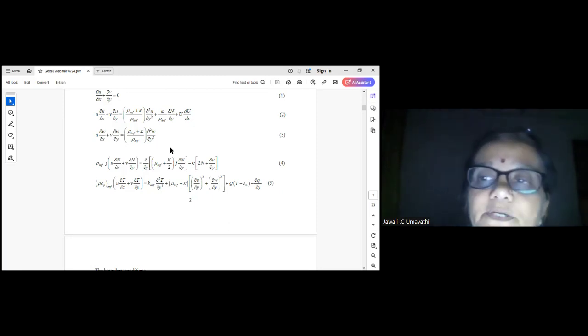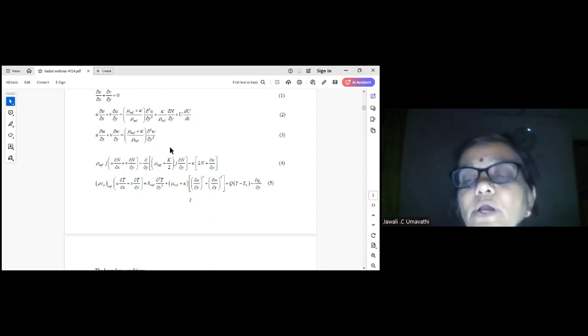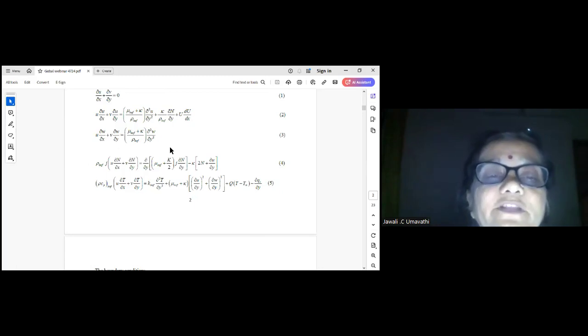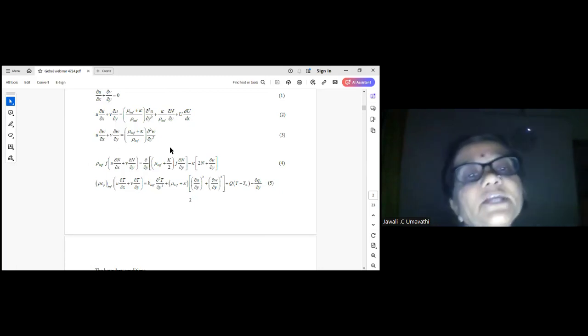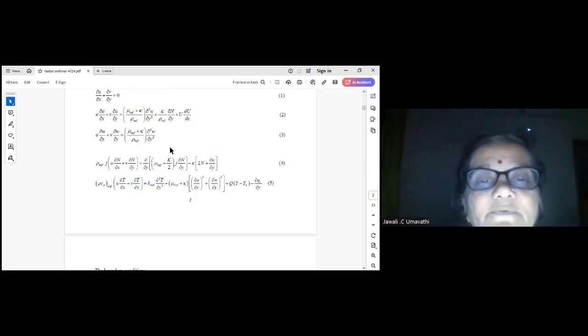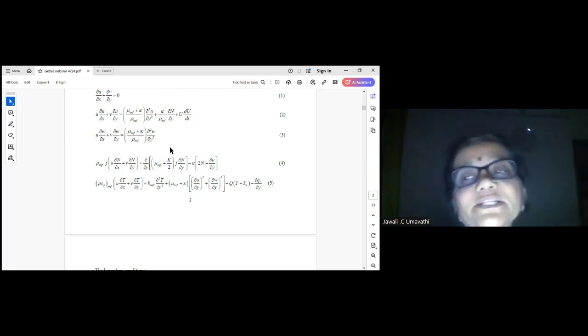So the physical properties of nanofluid and solids are completely different. The thermal conductivity itself is different. Then how do we consider that solid and fluid are homogeneous? They argue that because we are considering the size of the nanoparticles to be very small, we can assume the conductivity or properties of fluid and solid are equal.